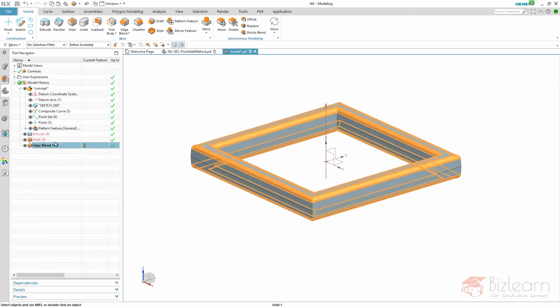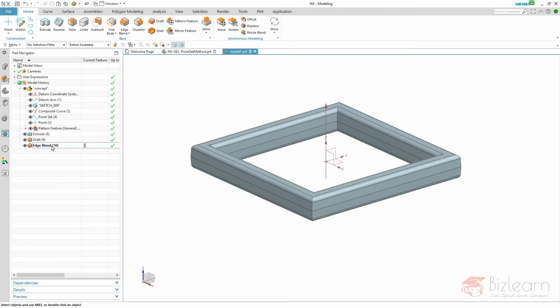Also here, it's a relation to an older object, to the face instead of the edge. Just imagine you create an extrude and a body will result from the extrude. So the extrude is the older element, body is newer. Faces result from the body, so the faces are newer. Edges result from the intersecting faces. So the edge is the newest element of your body. And if you create a relation via edge blend, for example, and relate to the body, you have created a relation to the possibly oldest object. Pretty cool, pretty simple. That's what we call horizontal modeling.